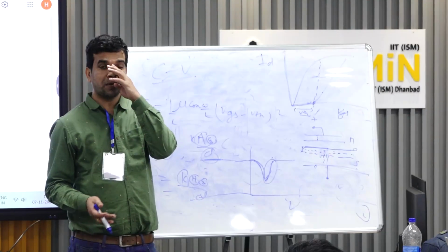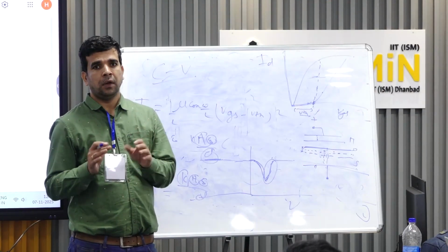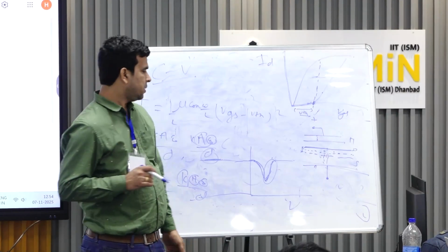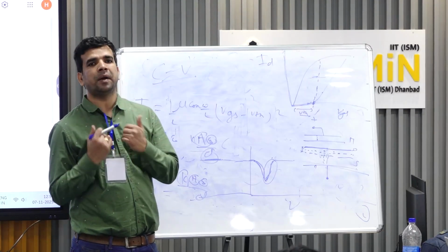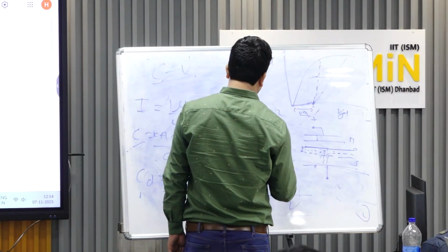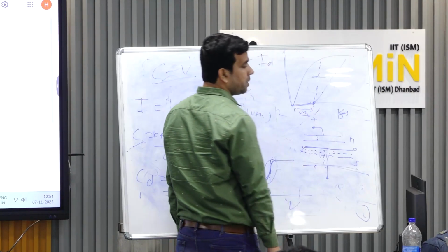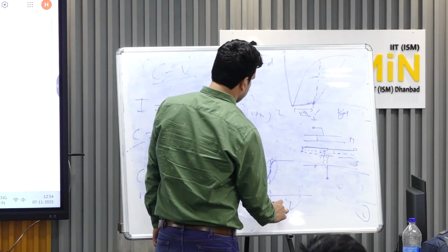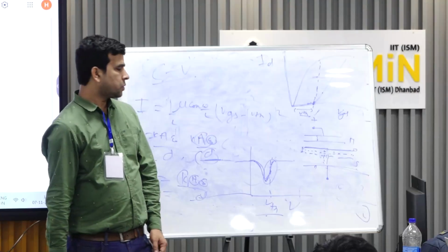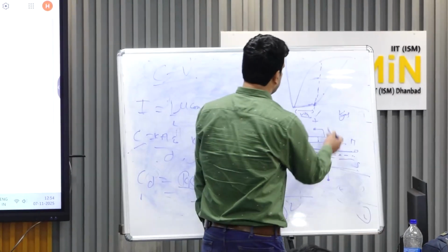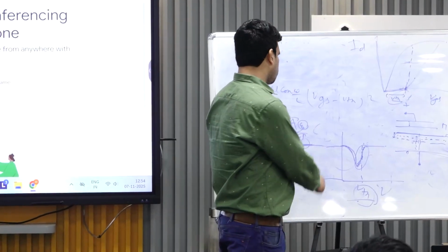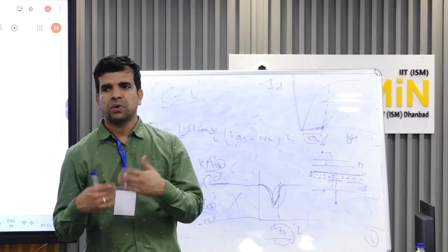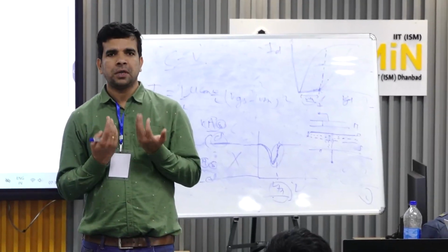So what is threshold voltage? Threshold voltage is where you get the inverting channel, and its carrier concentration should be similar to the previous concentration. It is the voltage at which your channel is completely inverted. So by doing CV characteristics, this can be your threshold voltage. Fine. Either you can find it this way, or that way. I suggest at the initial level, don't go for the CV measurement. Just do the IV characteristics, ID-VG characteristics, and you can find the threshold voltage. So now the threshold voltage is known to you. Fine.